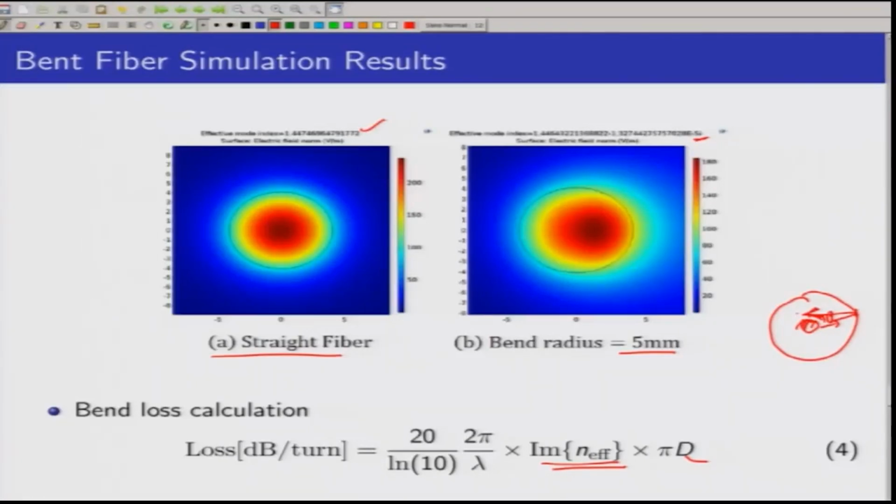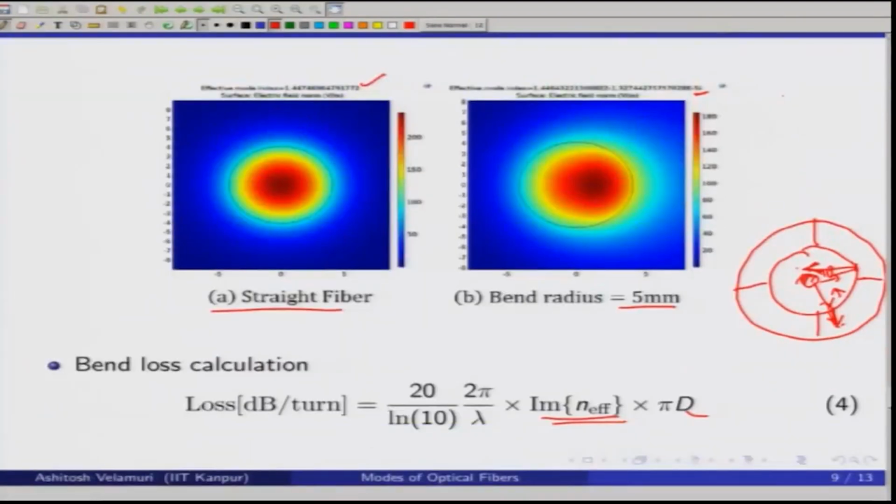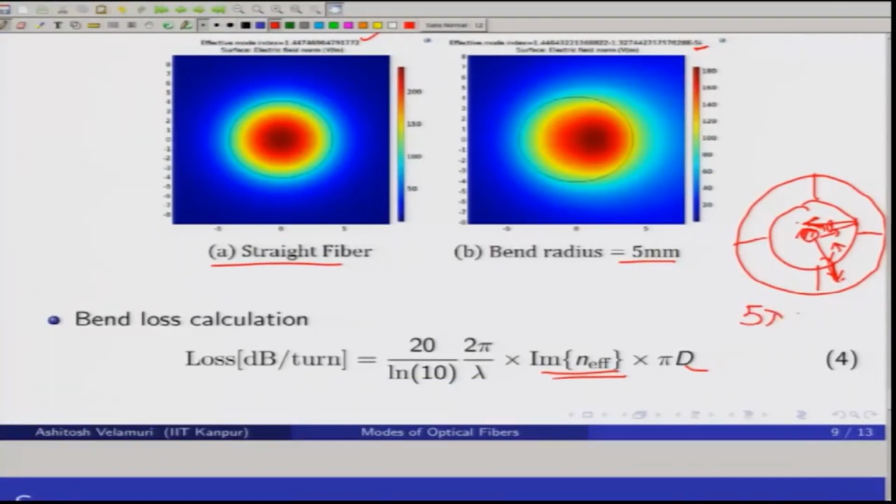So, in order to avoid this circumstance, we add a third layer, called a PML layer. What this layer does is, all the radiation coming from the core gets absorbed in the PML layer and no radiation comes out. So, we are basically removing unwanted radiation from reflecting back, which would distort our final output, and we are protecting our results. The imaginary part we obtain is after applying the PML layer, whose thickness is generally 5 lambda to 7 lambda, where lambda is the operating wavelength.